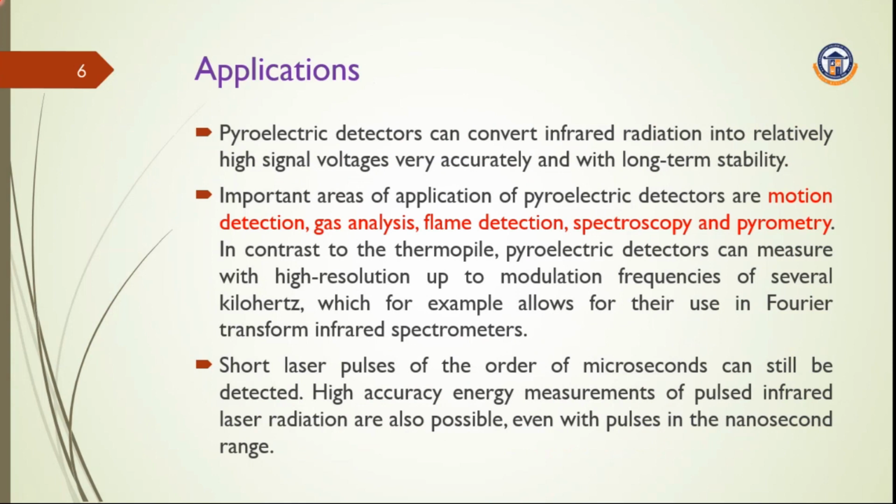Next, we see the applications of pyroelectric detectors. Pyroelectric detectors find major applications in gas analysis, flame detection, spectroscopy, pyrometry, and motion detection. In contrast to the thermopile, which is one type of thermal detector, pyroelectric detectors can also measure high resolution modulation frequencies up to several kilohertz. For example, it allows the usage of Fourier transform infrared spectrometers for measuring them. Short laser pulses of the order of nano or microseconds are also detected using these pyroelectric sensors.